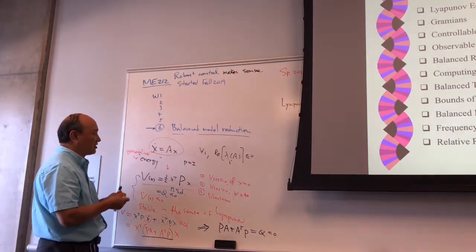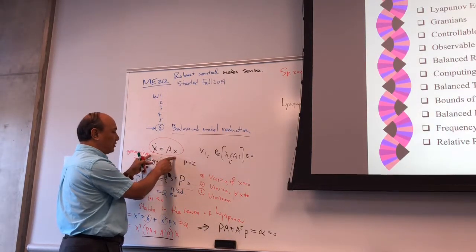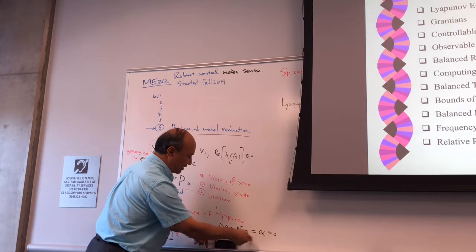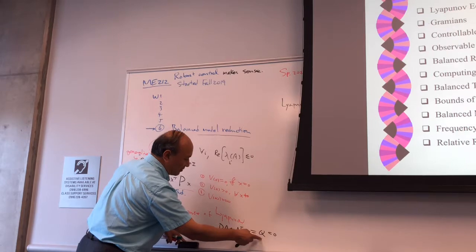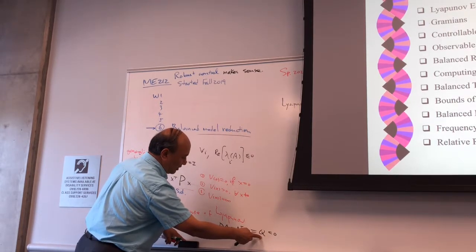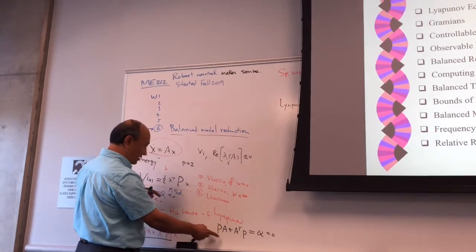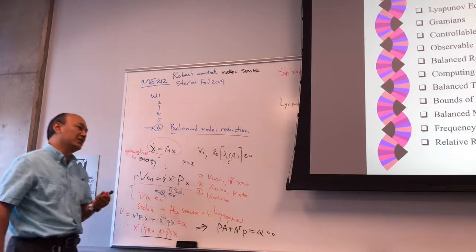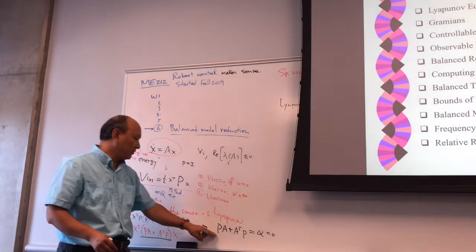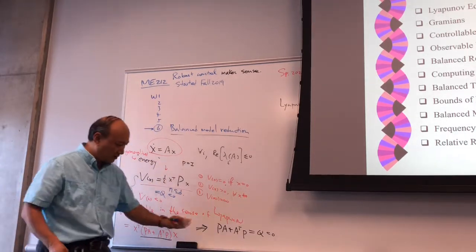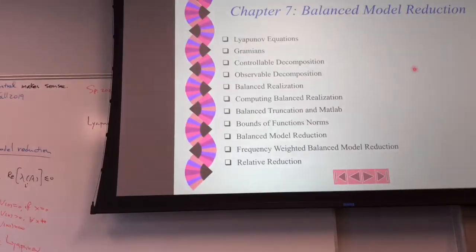So basically, instead of looking at the eigenvalues, we turn this stability question into a Lyapunov function question, saying that given a negative semi-definite matrix Q, can you find a positive definite matrix P to satisfy that? So this is called the Lyapunov equation. So the Lyapunov equation is based on this. So we are going to see it, and it will be very fast in the next.